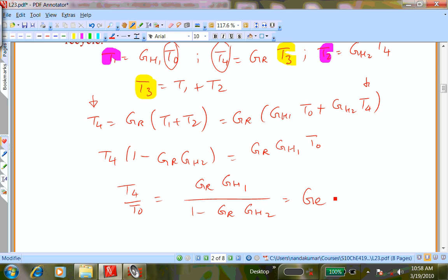Okay, so it's fairly simple algebraic manipulation, and unless it's a truly interacting system, when you write these equations, you will find that both equations have both the variables. Then it calls for simultaneous solution. But in a situation like this, it's normally sequential with the recycle, so you can eliminate fairly easily and get the effective transfer function. Any questions on that?